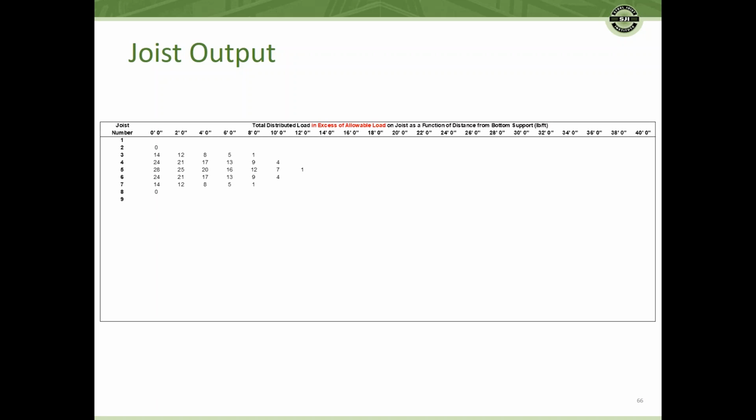But this also occurs at the joist ends, where the axial load in the top chord is less. So potentially these overloads don't really cause an overstress. However, if they get large, it's probably best to select the larger joist.